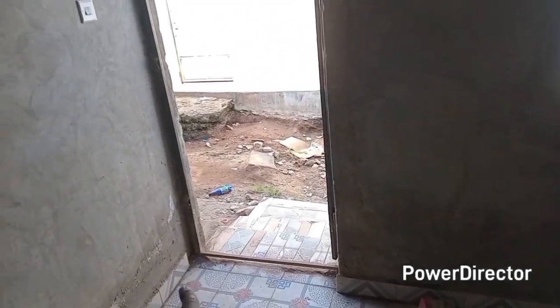So we are going to multiply the length up to here times the height up to there, and then we are going to deduct the voids, that is the door opening and the fourth, plus this window opening to get the net area now of the wall.